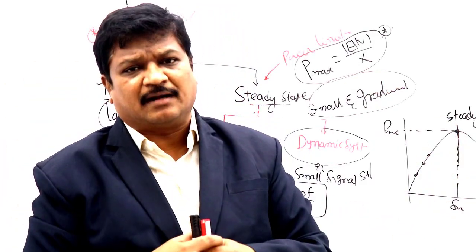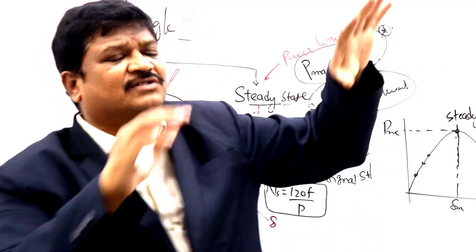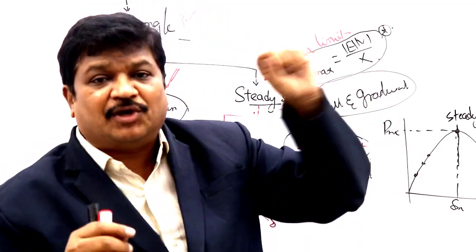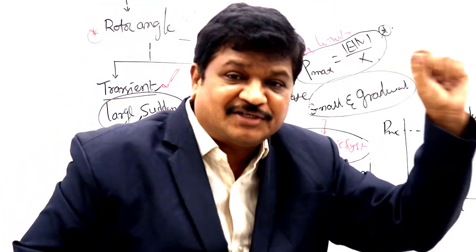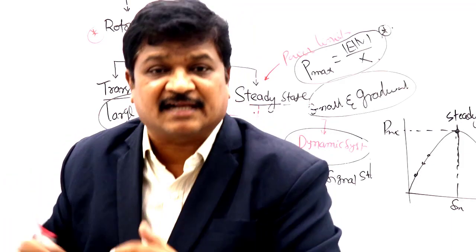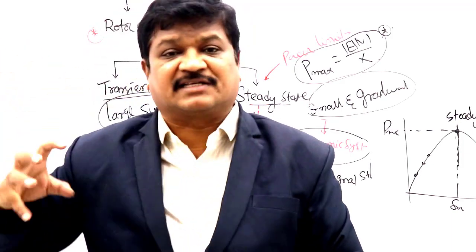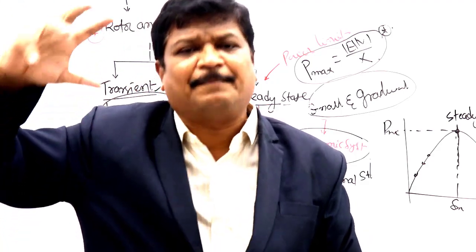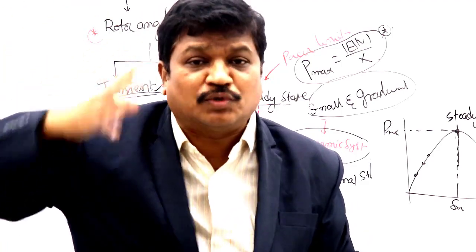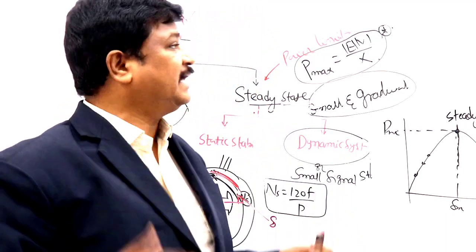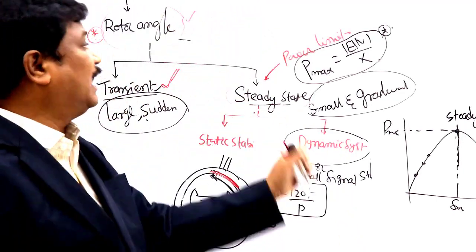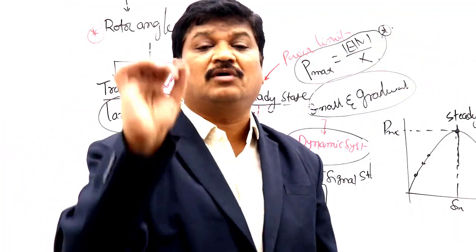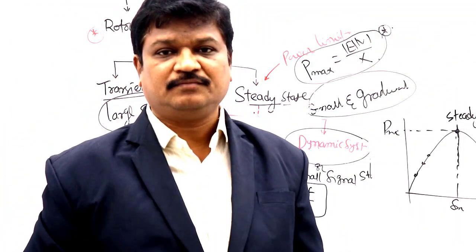Load is a regular one. In the morning you switch on your geyser. If it is summer, at night you are using AC. Suddenly you switch off your AC. And industries are shutting down. Load is shutting down. Such variations are more in the power system. We want to take care of that. We have to maintain rotor angle stability as well as frequency stability and voltage stability without damaging our equipment.